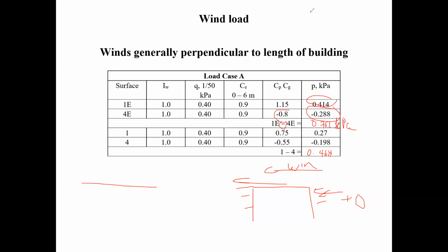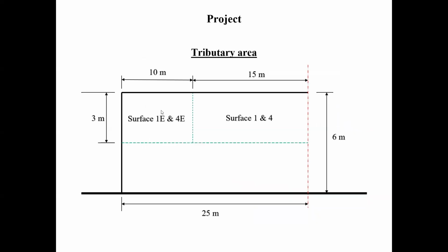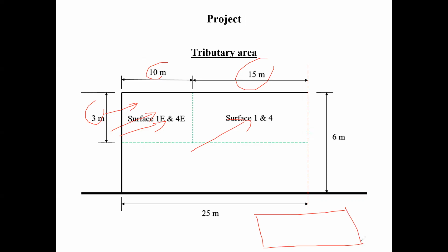Okay, so if we're looking at this, if I go back, right here, that's the pressure acting here of 0.072, and then here we have a pressure of 0.468 acting on this surface. So if I want to know the force acting on the surface, I multiply by the tributary area. In plan view, usually I don't get into this because you can use the roof as a transmitting mechanism of the lateral forces to the vertical brace here.